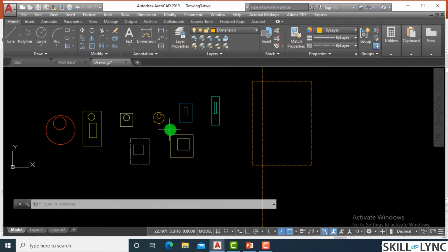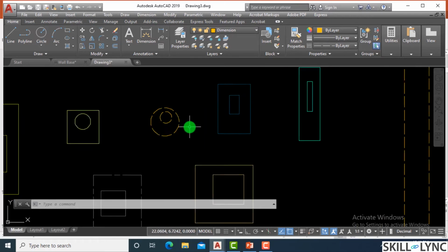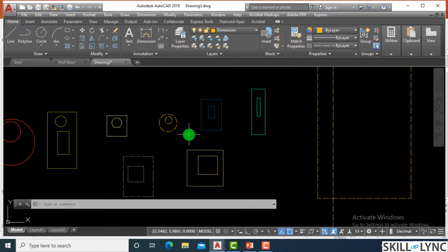Now the next property is the thickness or the weight of the line. Line weight means the pen thickness. We use a line weight in order to show the section lines, in order to show the outer lines. So in drafting, line weight holds a very important technique of demarcating section lines, demarcating thin lines and thick lines, and demarcating objects which are far and beyond.